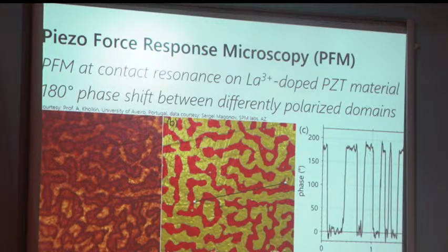And of course, advanced PFM measurements include something called dual actuation resonance tracking, where if your samples are susceptible to high voltage, you can perform something called a contact resonance PFM, where the signal gets amplified even at low voltages. But anyway, that is something called dual actuation resonance frequency.